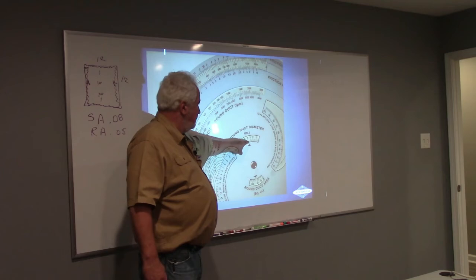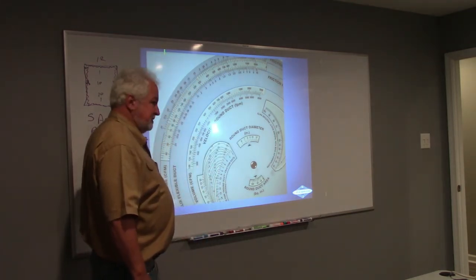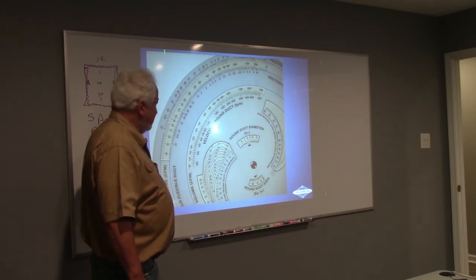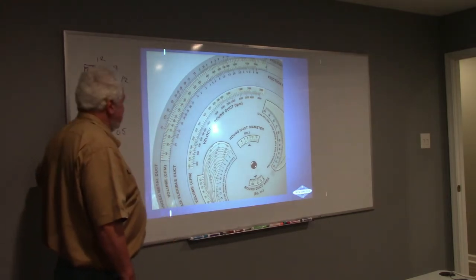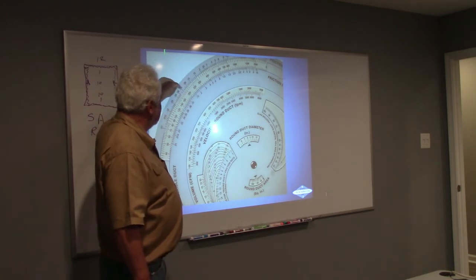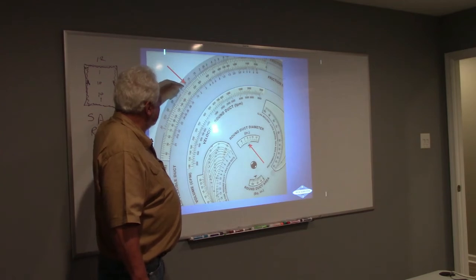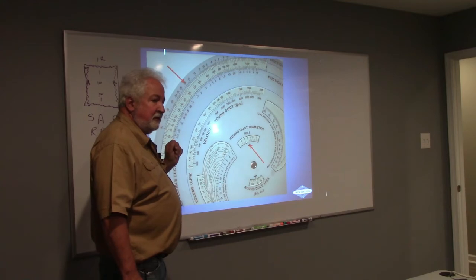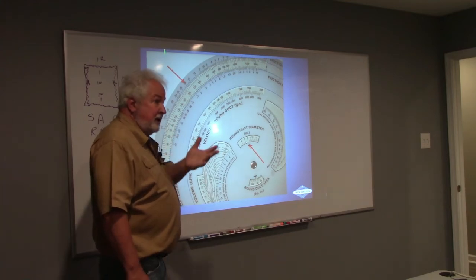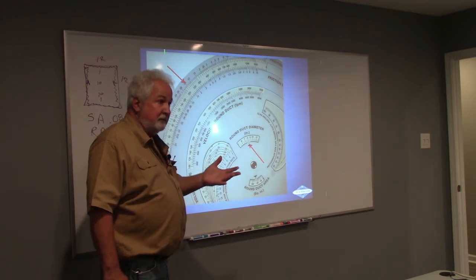When you go to 8-inch round, we're going to go to the galvanized metal duct because it's wrapped on the outside. Is that right? Yep. Galvanized metal duct. We said that we're going to look at the supply air at 0.08. So galvanized, go up to 0.08. Should be around 200. Does everybody see around 210, something very close to that? Good. Everybody all right with that? So an 8-inch round is going to get you about 210 CFM, as long as it's metal. Is everybody good with that?